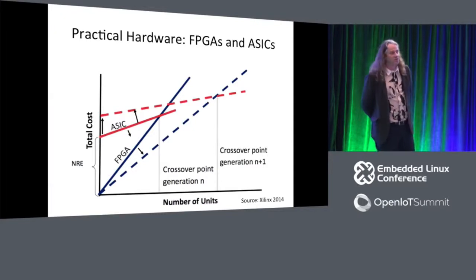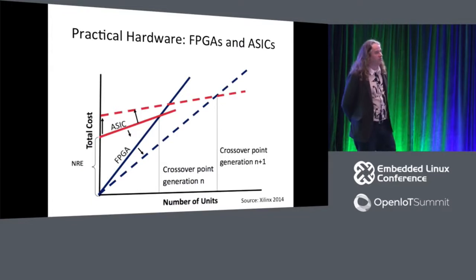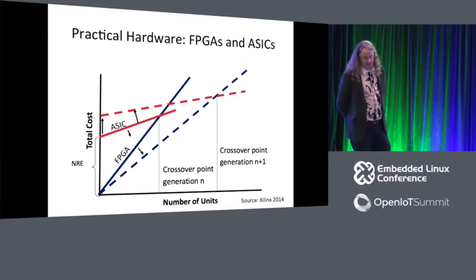The question becomes, what's your MOQ? What's your minimum order quantity for those chips? One wafer, in 6-inch or 8-inch wafers, which 180 nanometer usually is, you can probably put about 3,500 chips on. And that wafer is $1,800. So that's not too bad. And you probably need to buy a boat of wafers, which is 12 or 18.